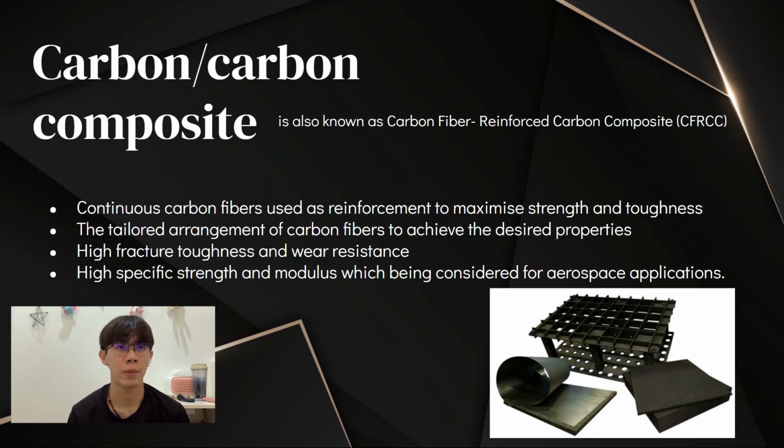Now I want to introduce the carbon-carbon composite. It's also known as the carbon fiber reinforced carbon composite, CFRCC. It consists of carbon fiber embedded in a carbon matrix. The continuous carbon fibers are used as the reinforcement to maximize the strength and toughness. The arrangement of the carbon fiber in a standard orientation within a continuous carbon matrix is used to achieve the desired properties. The carbon-carbon composite has high fracture toughness and is wear resistant, but the most attractive properties of the carbon-carbon composite are their high specific strength and modulus, with increasing consideration for aerospace application.